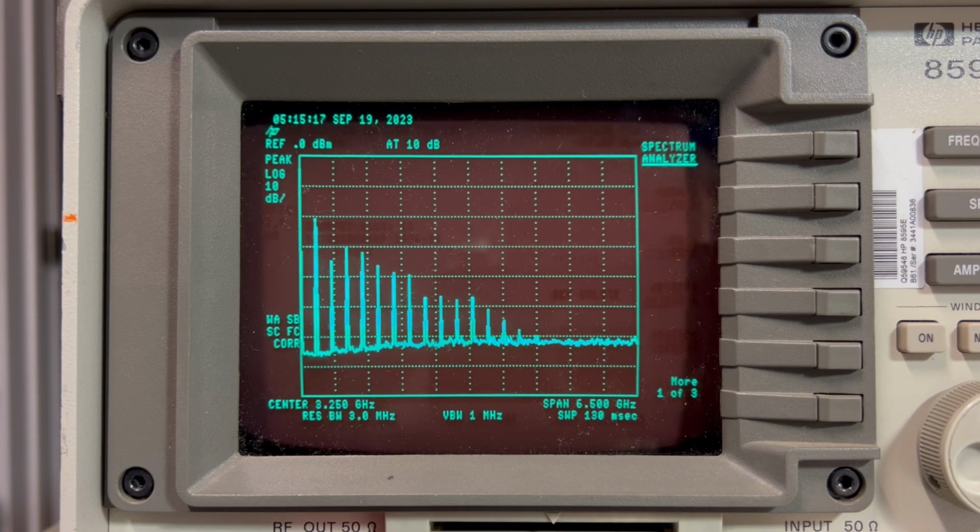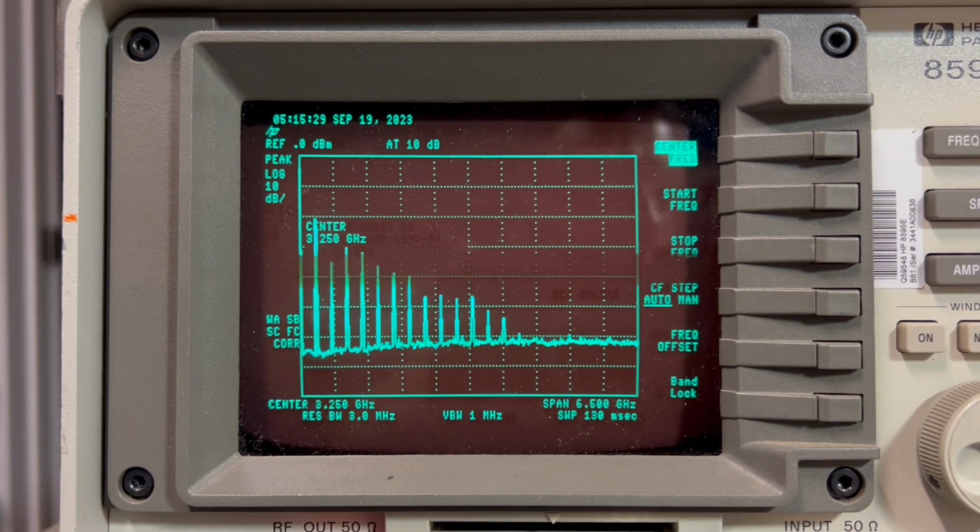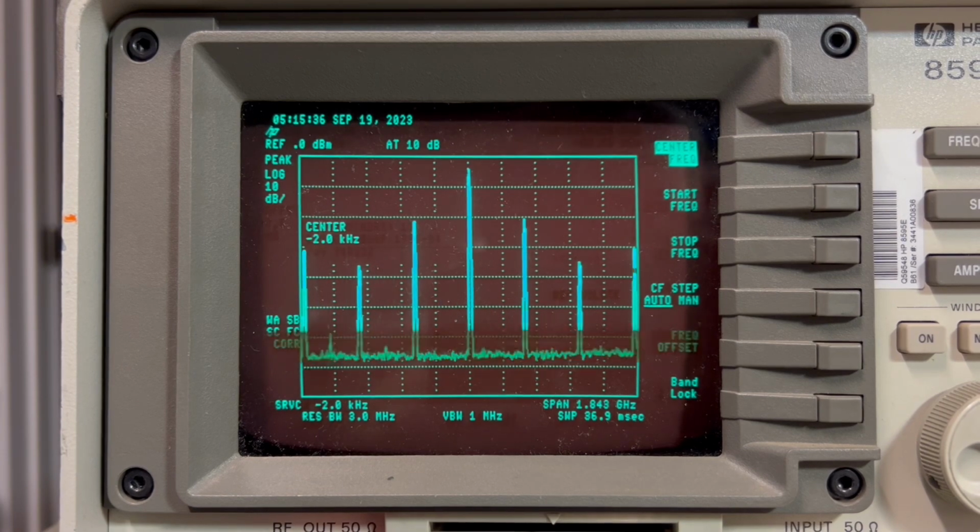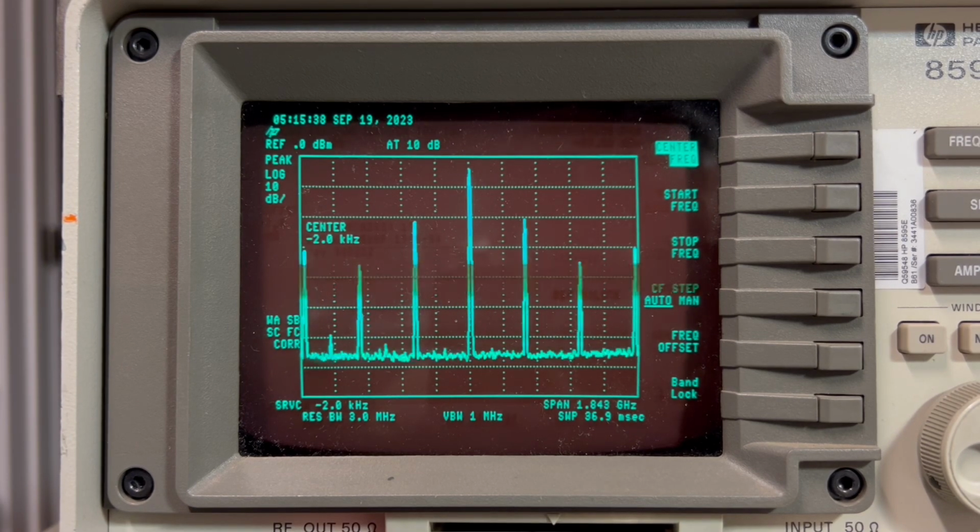So we're going to enter the flatness correction data that we've collected here. I've already put the instrument back in preset. We're going to enter the passcode for making changes to the correction parameters. All right, then we'll access the data.